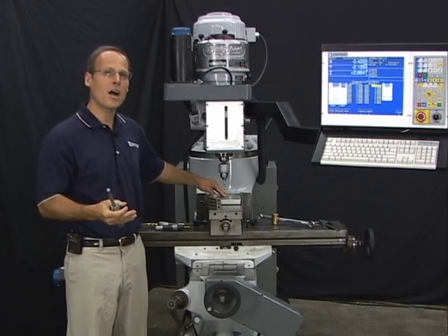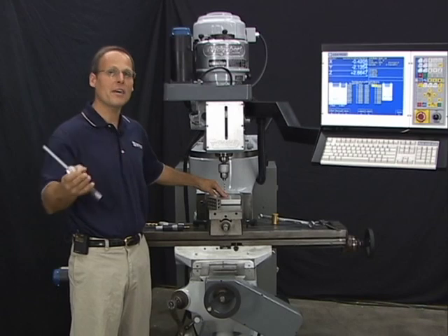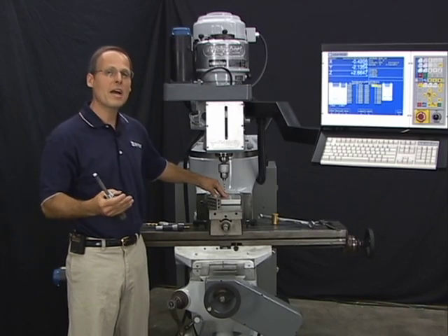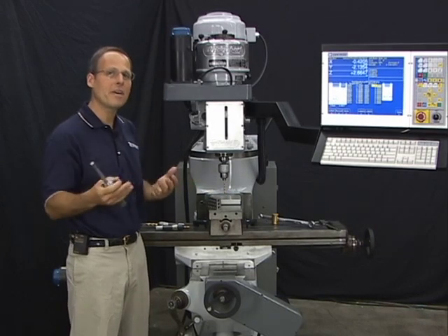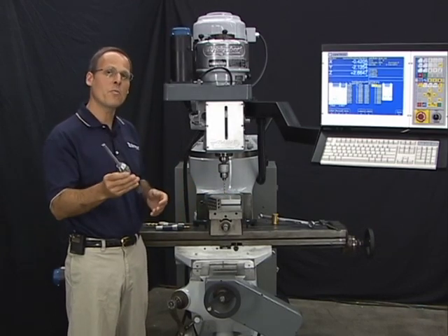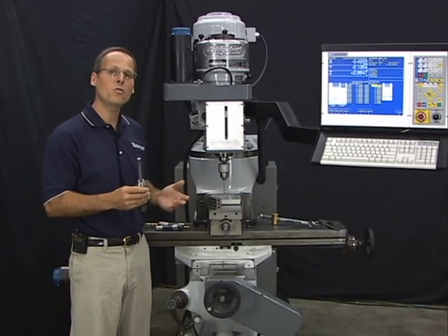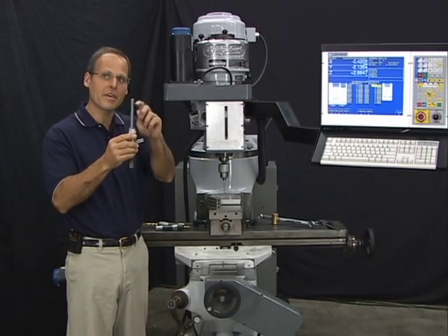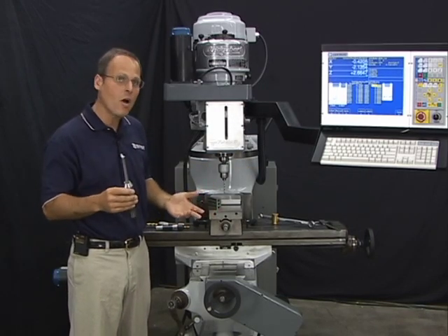So if you're a job shop and you're making 2 or 3 or 5 different parts a day, let's say with 5 tools each, you have to reset those tools each time. So you're setting tools 25 times in a day. With the Centroid reference tool method, it reduces setup time, because if I have those 5 tools, I only have to measure them once against the reference tool. I can then machine as many different parts as I want.